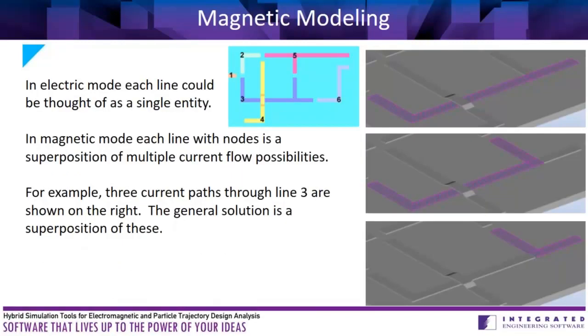So one can more broadly describe that as bringing metals, any big pieces of metal such as a copper sheet or case parts, close to the board will affect these mutual and self capacitances that exist. The same thing will happen in magnetic modeling. So let's examine a magnetic solution here.